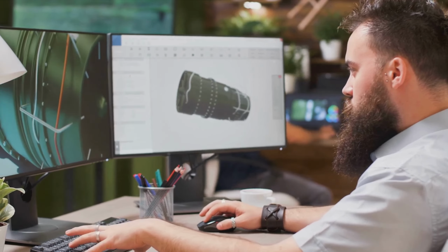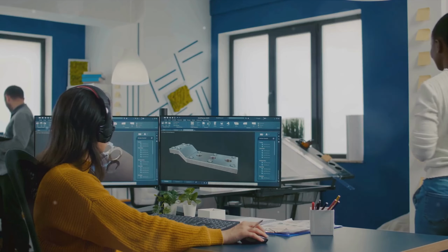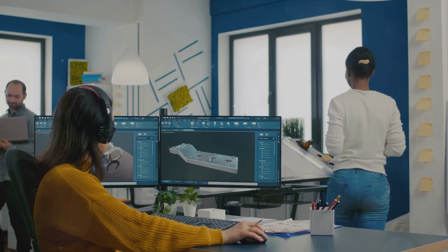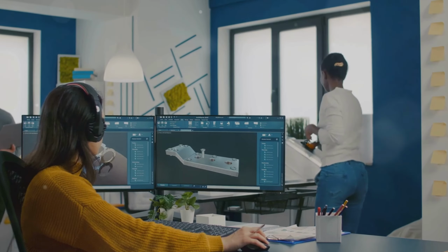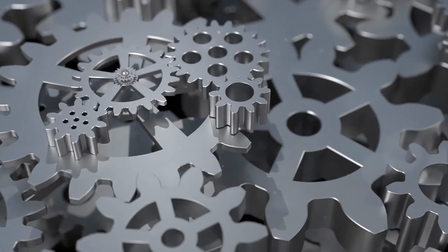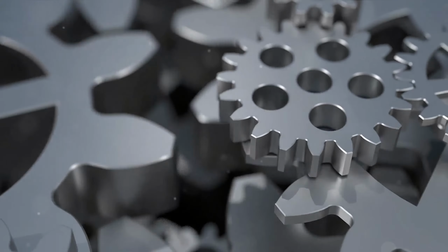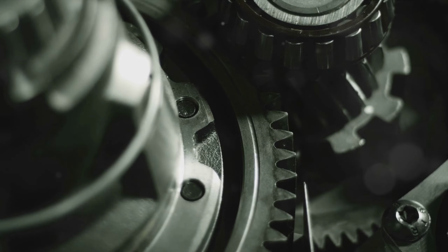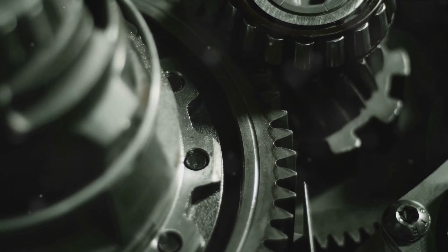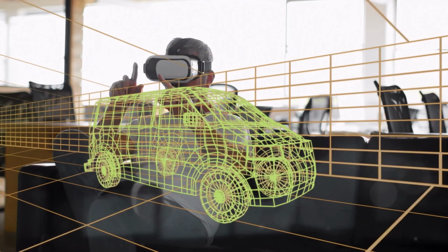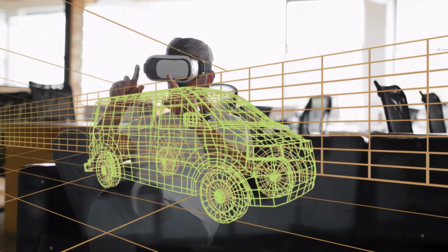The MRF model then solves the Navier-Stokes equations separately in these zones, considering the relative motion between them. Both models are powerful tools in ANSYS Fluent that allow engineers and researchers to accurately simulate complex fluid dynamics scenarios.